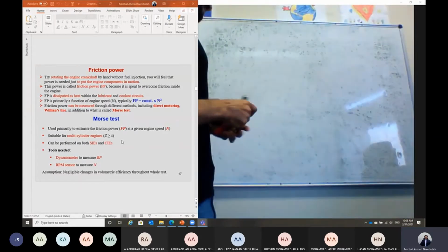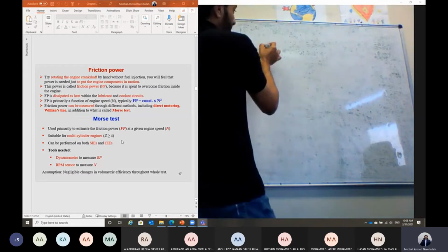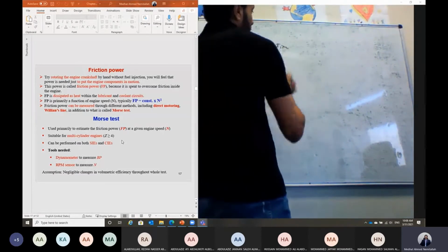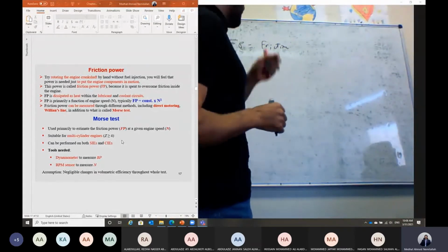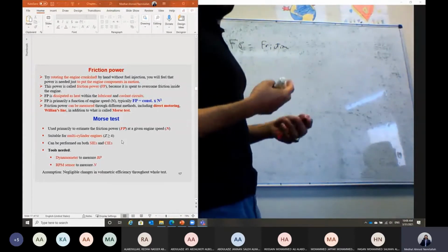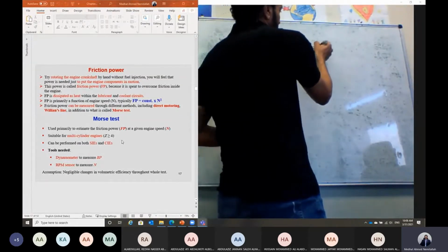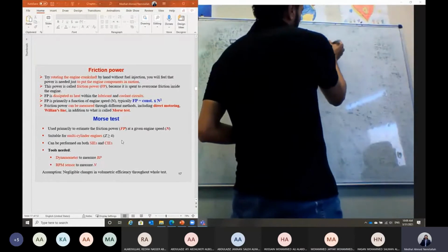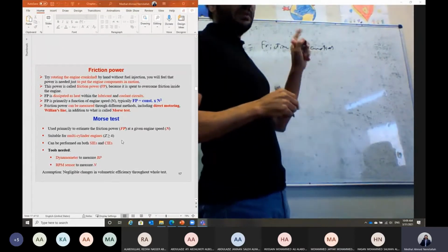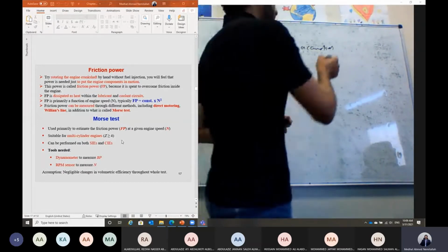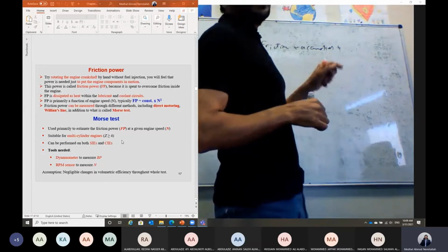And as we said here, Shabab, this friction power is equal to the rubbing friction losses, the friction between the piston as it is moving inside the cylinder, and the piston and the cylinder, and also the friction between the molecules in the gas phase inside the piston itself. Also, it is equal to the power required to run all of the accessories within the engine, like the fuel pump, as we said, compressor, cooling water recirculation pump, all of which take part of the output power.